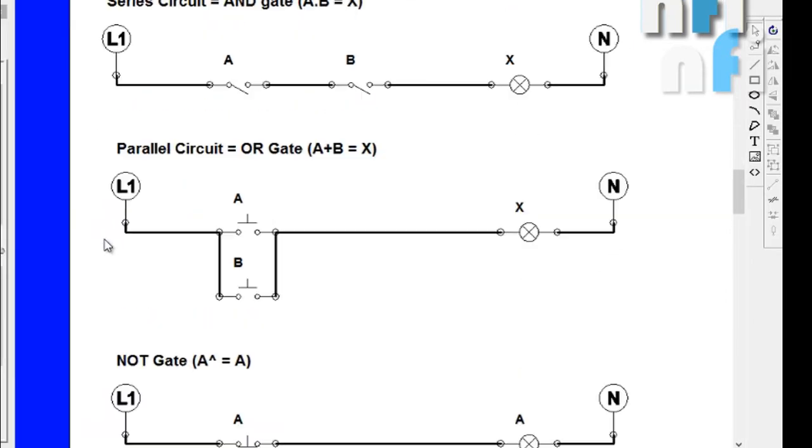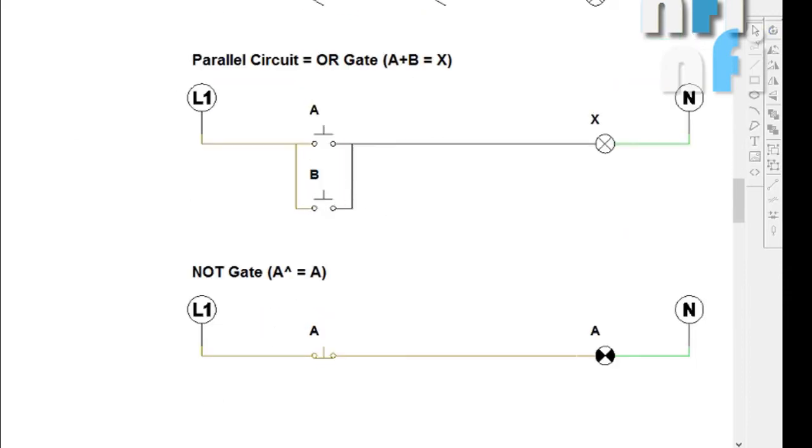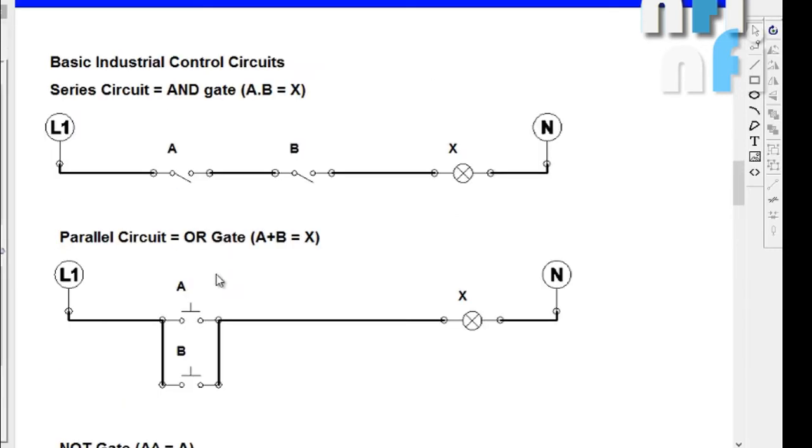So now let's move on to latching, the principle of latching. Now suppose, what is latching? Suppose I want that if I press this button here and if I release, this should remain on. It should not get off. It should remain on just by the pulse input. That is called latching. So how to do that? Let's see a latching circuit now.